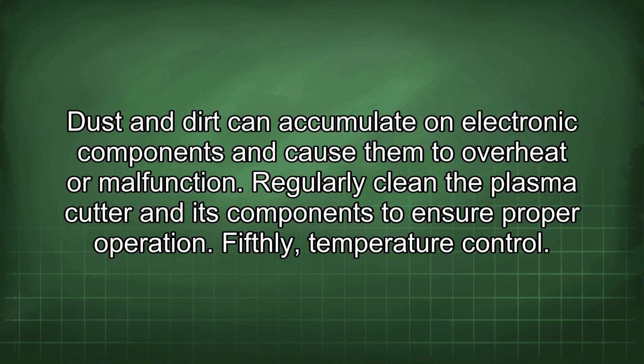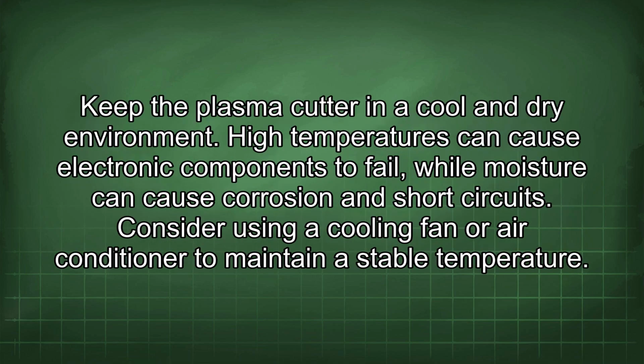Fifthly, temperature control. Keep the plasma cutter in a cool and dry environment. High temperatures can cause electronic components to fail, while moisture can cause corrosion and short circuits. Consider using a cooling fan or air conditioner to maintain a stable temperature.